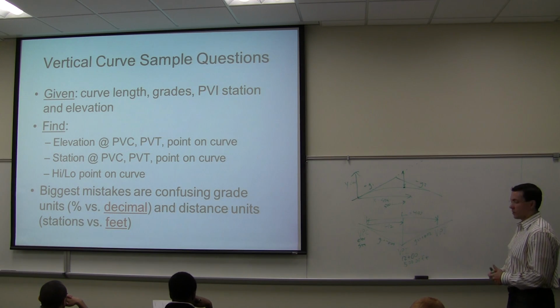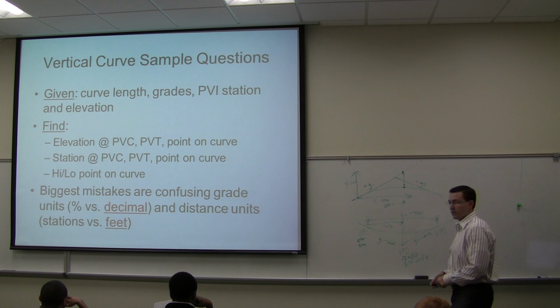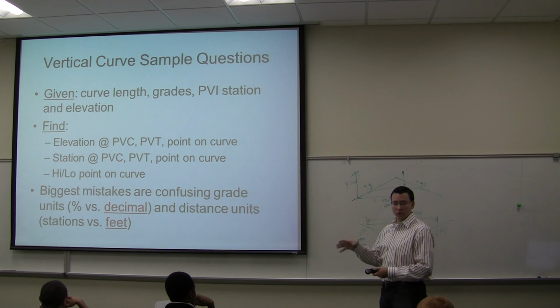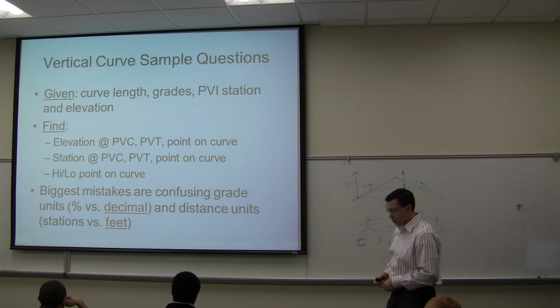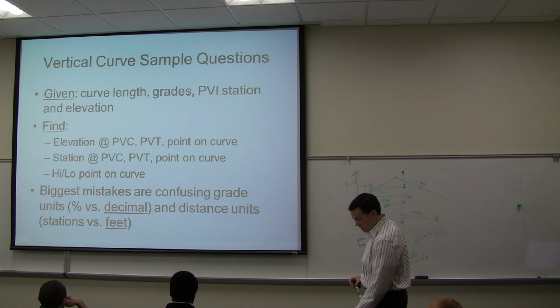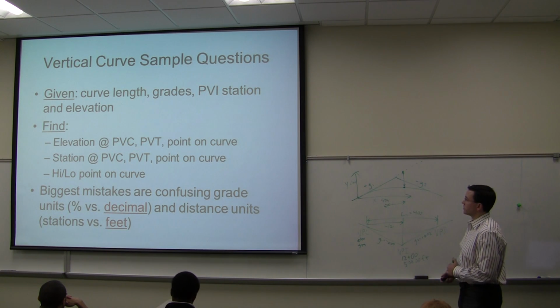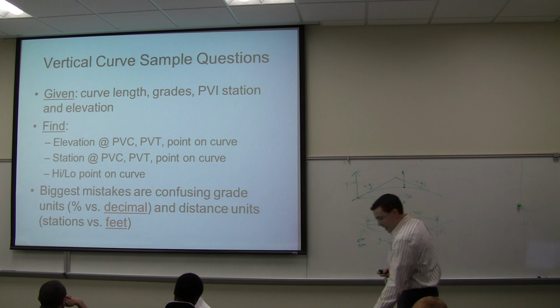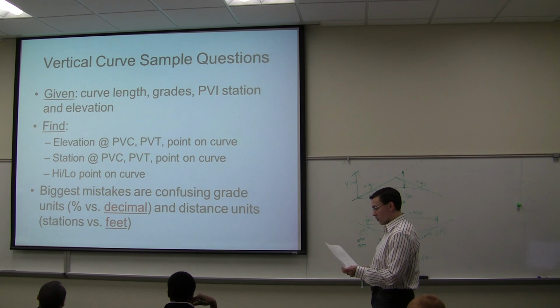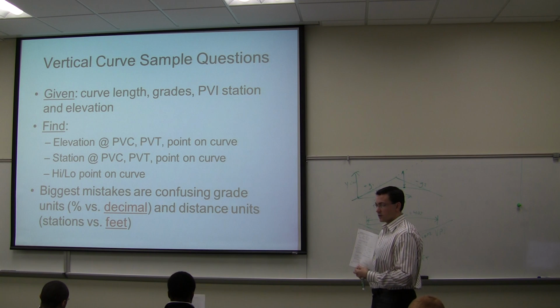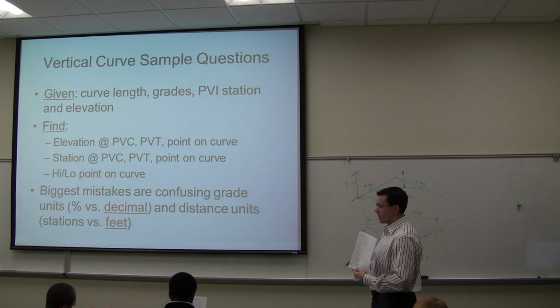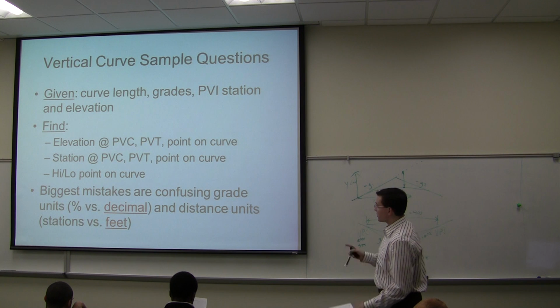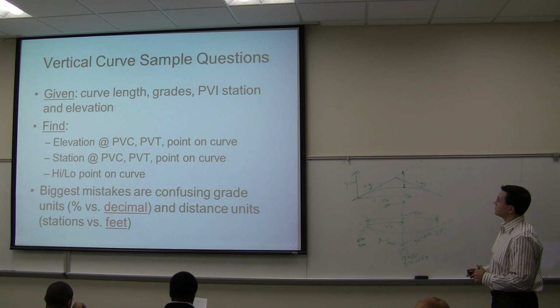The quickest way to calculate the curve length was that L equals KA method. For K, there's a table, you can look up the K factor depending on what the speed is and whether it's a crest or a sag curve. They don't give you the K values in here, so you're probably not going to have to use that. But on this first page, you do have the equations for calculating curve length the brute force way. So if you remember the S greater than L, S less than L, stopping sight distance greater than the curve length, you've got to go through and do both calculations to see which equality is satisfied. I think I've got a few examples of that here in a minute.